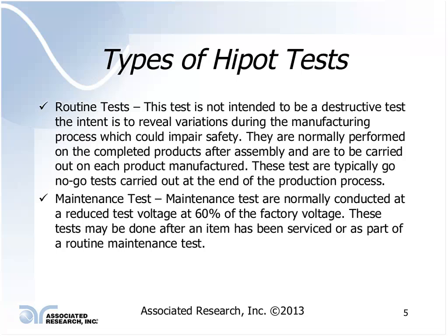The test may be done at a higher potential. It is very common to see an increase of maybe up to 20% over what the potential is during a design test. You might see an increase in the test potential 20% higher for a routine production line test.